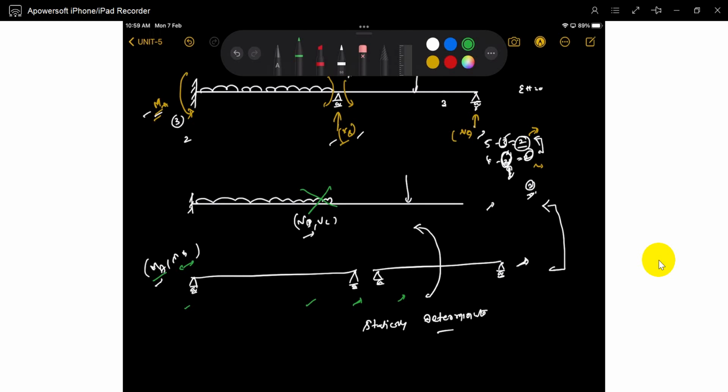That's the first idea. Next, you have to find out the fixed end forces in the stiffness matrix. Here, fixed end deflections. Understood? Fixed end deflections means, at that location you have to find out the fixed end forces. Here fixed end deflections. So you choose two deformations, you choose two indeterminacies. What are MA and MB?